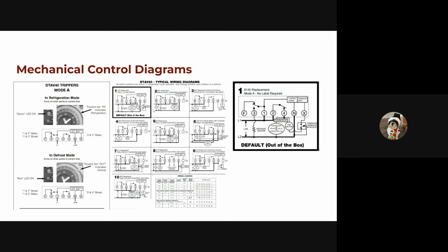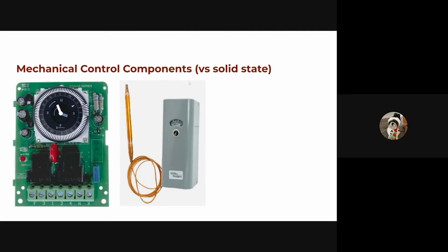You'd have some kind of thermostat. It's still a thermal input of some sort, or you might have something like this. I think I've seen something like this out at the rack houses at the compressors. Maybe a different form factor, but something similar. Usually when you see those in the rack house, that's for actual exhaust fans in the rack house. Oh, okay. We rarely use a T-stat like that. We did before they came out with the KE2s. We would use a lot of those in walk-in coolers to control the temp, and that strictly controlled the liquid line solenoid. Okay. Just for temperature.